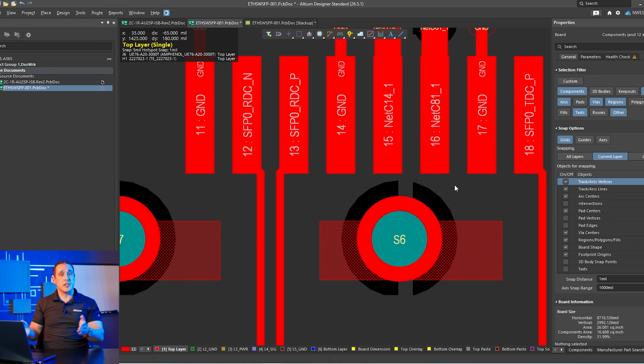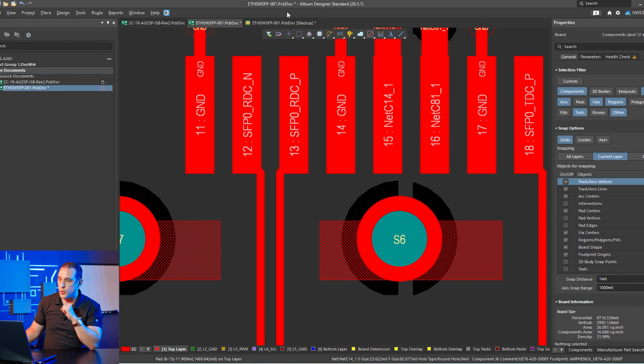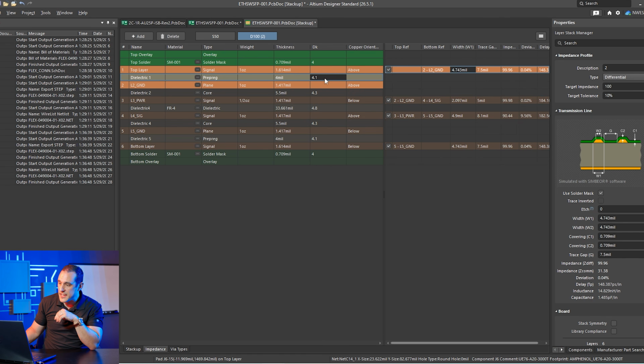So this upper limit on the trace width is going to put a constraint on the thickness of the dielectric that you can use in the stack-up. But there's one other lever that we have to tailor the trace width. Remember that that is the gap between the traces.